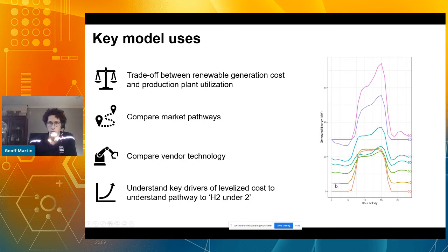So as we turn on more wind, we get 40% utilization, and we can actually run the plant at night as well. And you can see how that increases as we increase the utilization. We turn on more and more wind, increase the solar as well. And then to get up to 80, 90% utilization, you need batteries because there's going to be periods at night where there's no wind and obviously no solar, so you have no energy.